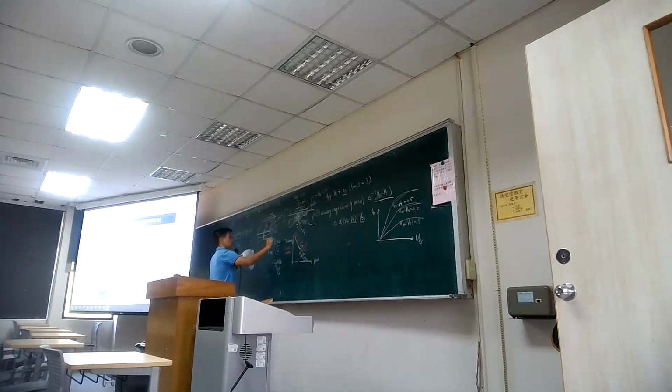Okay. And then typically epsilon oxide, if you are interested, is 3.9 multiplied with epsilon naught. What is epsilon naught? 8.85 times 10 to the minus 12 as a coefficient. If you are interested, you can also write 3.4 multiplied with 10 to the minus 11, if I'm not wrong, in farads per meter, not squared. Maybe you can check. I'm not sure if I have the right typing here.